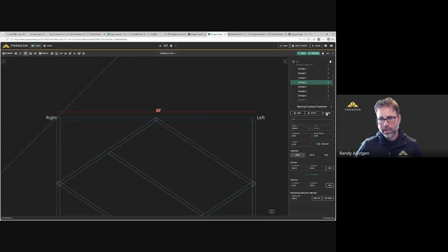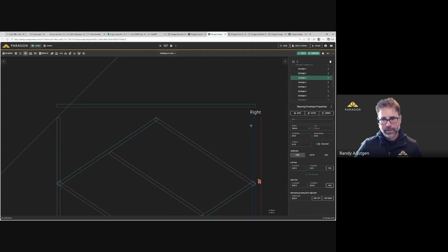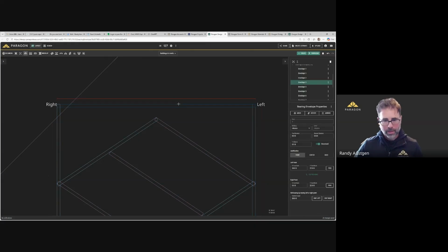So you can move, rotate, mirror. And I've been using mirror a ton. The first one I'm going to do is move. So for example, I could translate this, translate being the dimensions in which you want to move things. So if I wanted to move this up 2 feet, there I can move it 2 feet. If I wanted to duplicate it, I can either apply that and it just moves it. And here we're going to have some fun, selecting both of those walls, holding down Shift, extending those through. And then another way to do this, hotkey being Control M.